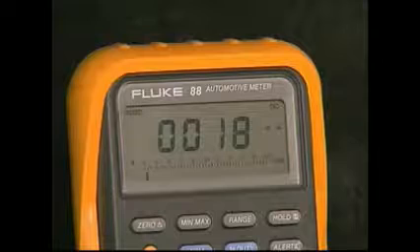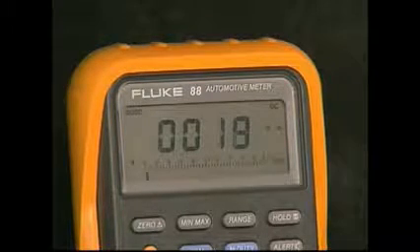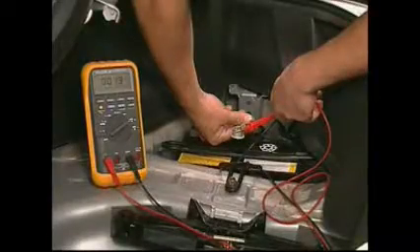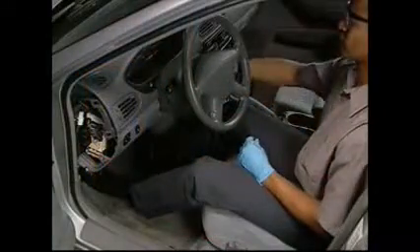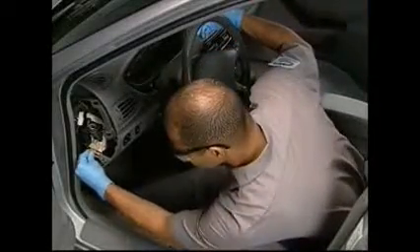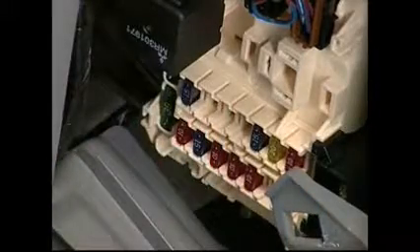Most digital multimeters are protected by a 10-amp fuse to prevent overloading the meter. Typical parasitic draws are less than 5 amps. Prior to installing the ammeter, make sure the power to the circuit is off before cutting, unsoldering, or disconnecting the circuit, as even small amounts of current can be dangerous.